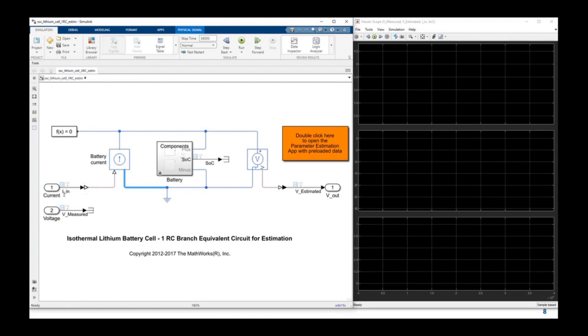So here we have an input current that is a reference current that we have measured on a real battery, and then we provide this input current to our battery. The only thing we need to do is use our Simulink signal in a battery current ideal source. This one will convert the current into a physical signal, and then we will connect this to the battery.